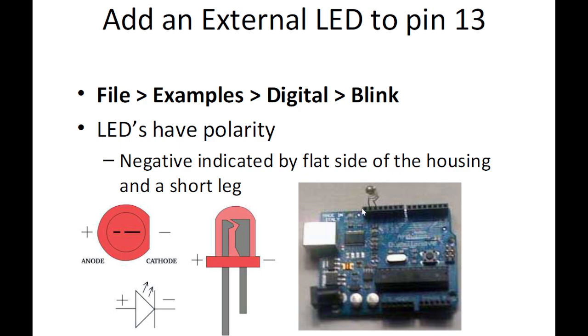But I highly discourage making a connection like this, because it can damage your LED easily. So this is not a good kind of a snap. I prefer to have on the anode side or on the cathode side a resistor of 100 ohm or 200 ohms or 300 ohms, just to limit the amount of current flowing through the LED.